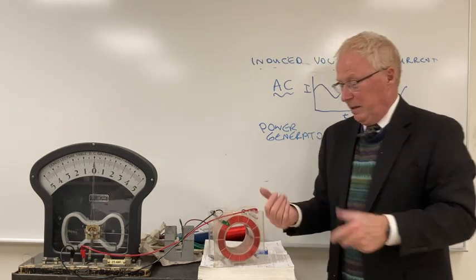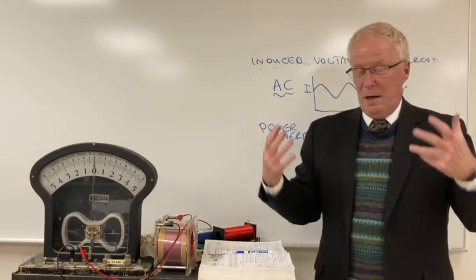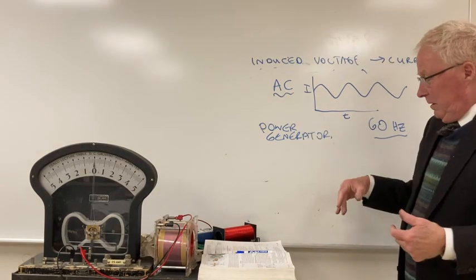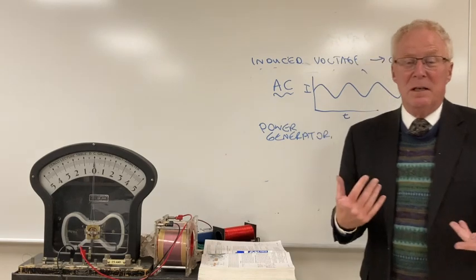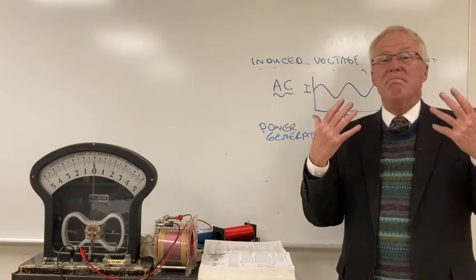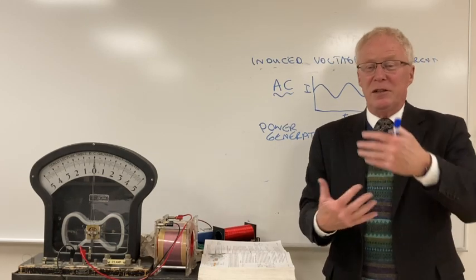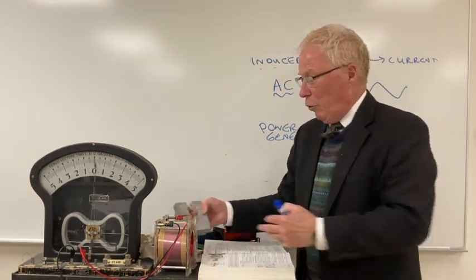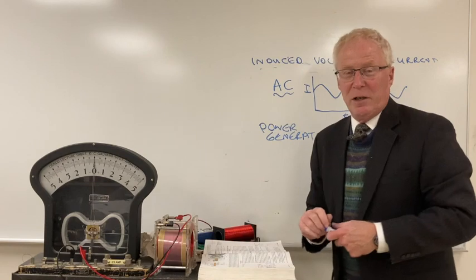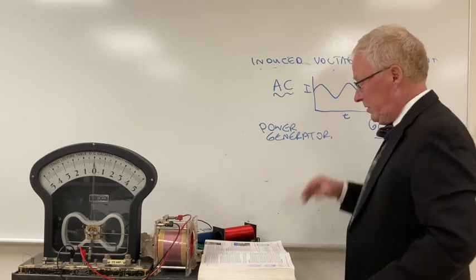And so you've got to turn that magnet in there. How do you do that? Well, that's the whole principle of the coal-fired plant or anything: to produce heat, which turns water into steam, and that steam turns a generator, which then produces AC power. Whether it's a coal-fired plant, gas-fired plant, or nuclear power plant, the whole point is to get a magnet rotating in a very large coil, very quickly, and you can generate large amounts of power, right? And so you end up with this AC current.